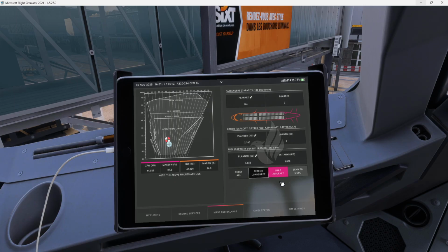So what does it mean? Capacity usable, what the aircraft can take of fuel, is 19 tons, and SG is the density. You know, guys, to go from liters to kilograms, you need to multiply liters by the density factor 0.8 in order to get the fuel in kilograms. And during cruise we will discuss what zero fuel weight means and all this stuff in general. So let's load the aircraft in 7 minutes.